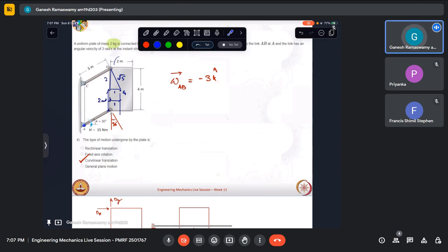By virtue of these two being equal and parallel, we know that this cannot support moment. If this is indeed applied with a moment, then these reactions would have to be mobilized accordingly. Yeah, that's what I'm saying. You are applying a moment to this plate. In this case, it cannot have a rotation about its own axis by virtue of this connection, in which case there will be reactions appropriately mobilized to counter that moment.